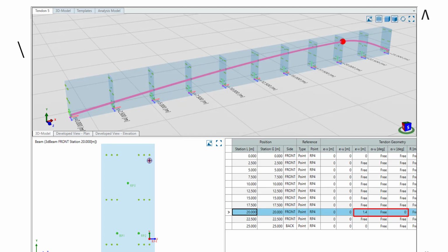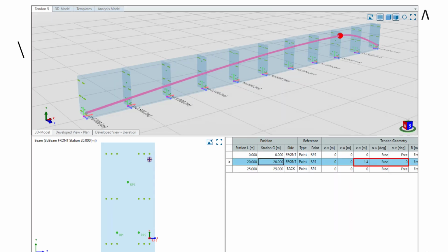The difference why I wanted to show you this one is simple. In the geometry it's no big difference, but in the analysis it would be different. When you want to go with your model and create an analytical result out of it, meaning pre-stressing, inner forces, or also construction phases, then it matters. Then you need to think, okay, where you want to have the tendon link to the structure. Do you link it to each cross section, or only to a few of them? This depends on where the outputs will be more or less in detail. So this is what I want to give you along at this point.